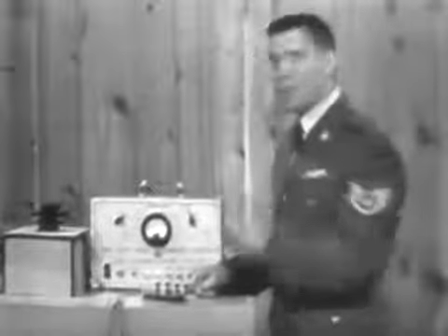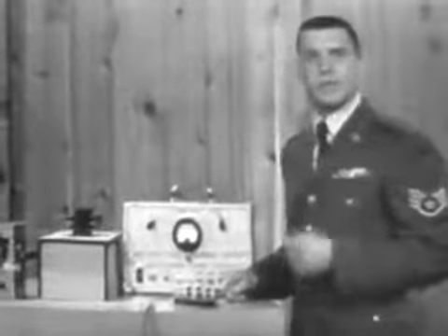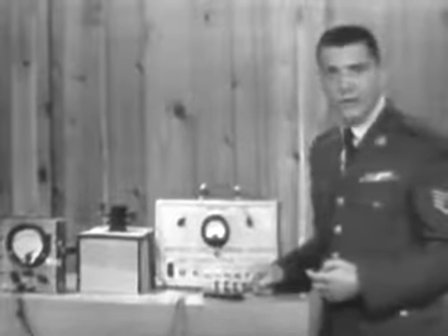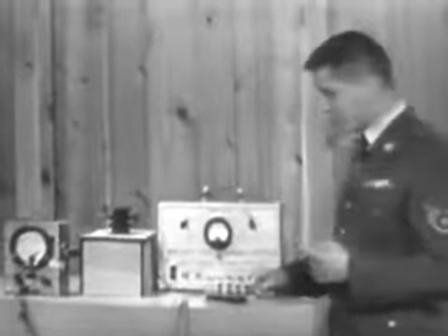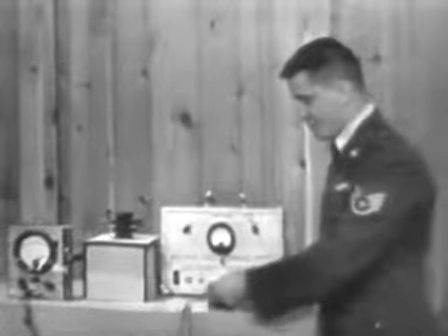The big difference in these 2 windings, however, is that one of them is shorted and one of them is open. So let's use our ohm meter and see if we can tell which is which. Now remember, the PSM6 has already been set up to read resistance on the ohms times 1 scale. So let's go ahead and check the resistance of the 150 turn winding first.